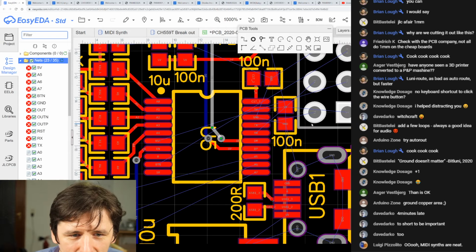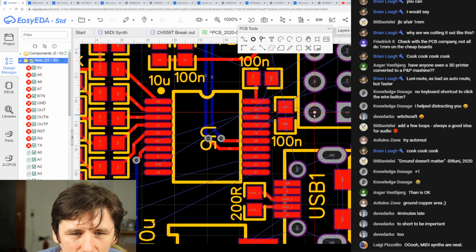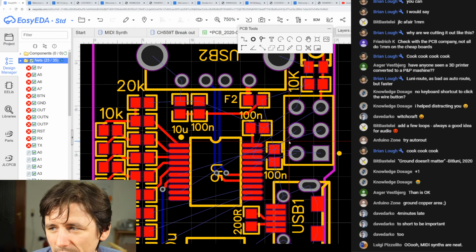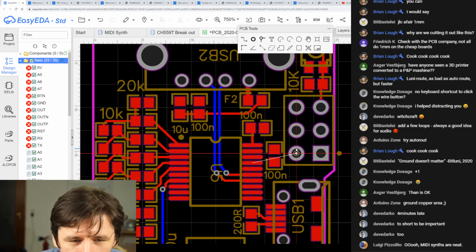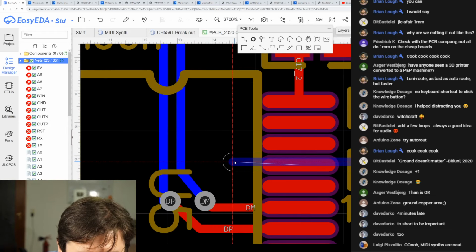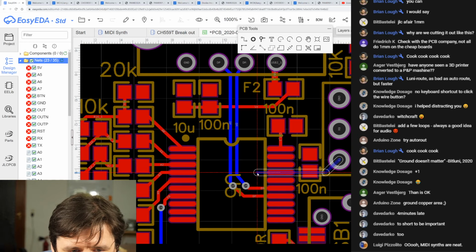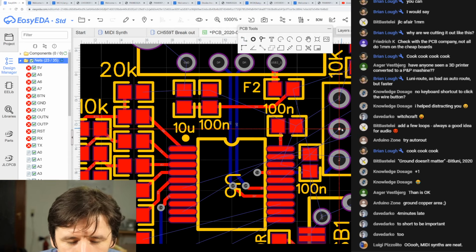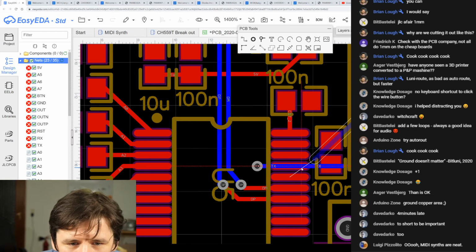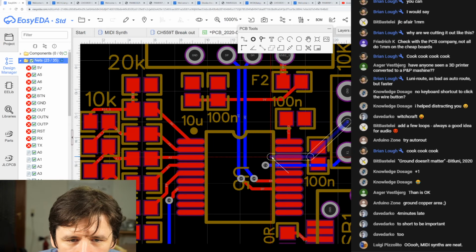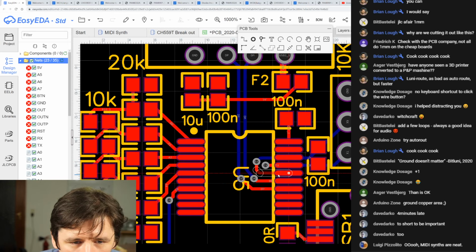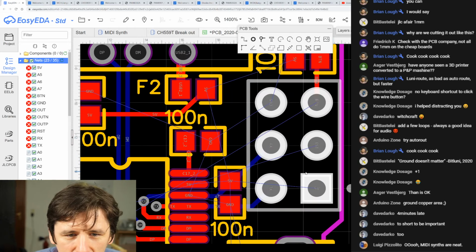Okay, now we have to route this connector here. I think I will do this on the bottom side. That's not really important, and we have through hole stuff here, so it's easy to route that. Yeah, can you see anything? Yes. Okay, bottom B, and which is TX? Doesn't show here. Put it like this, top, and then it's going back and forth there. This is TX, then we need RX, bottom B. We need to go there, so we are going like this, there. Yeah, switch to top, like this and that, and we are done with TX and RX.